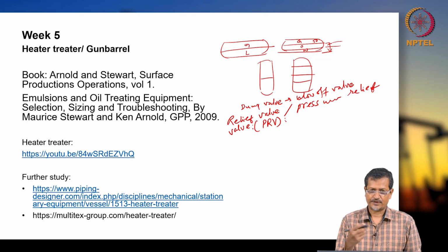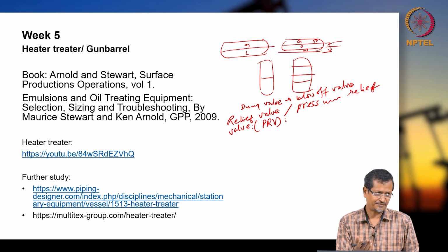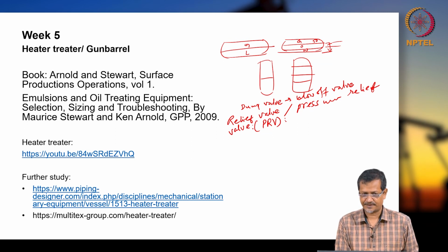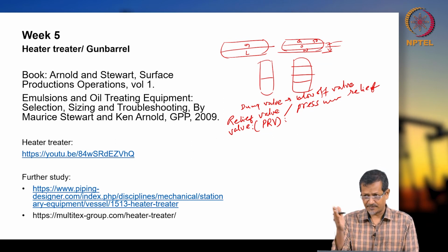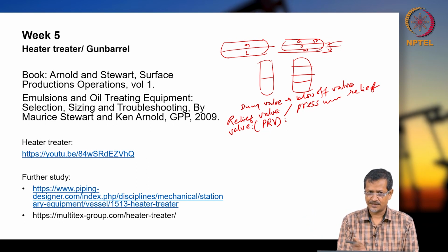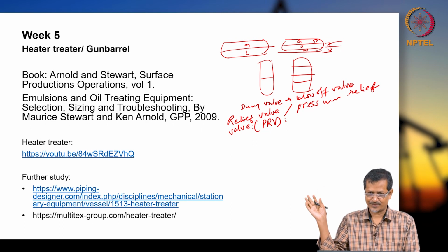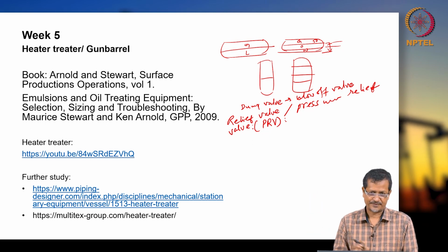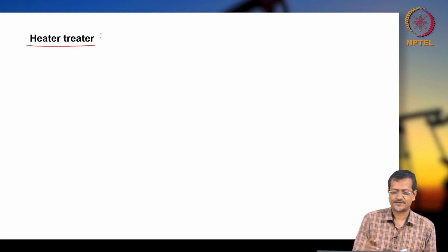For example, a pressure cooker will have a pressure relief valve, otherwise it will be completely unsafe. Your separator system also will have that sort of valve. Say the dump valve is not working, or suddenly pressure is going up, temperature is going up. In that case, your pressure release valve must work so that it reduces pressure quickly and the system will be safe.